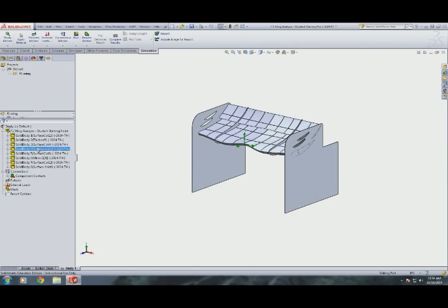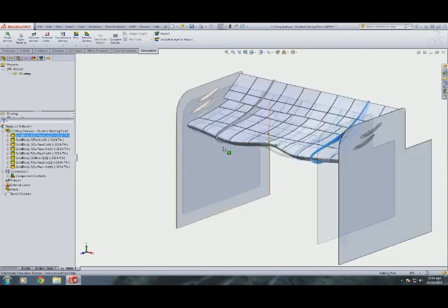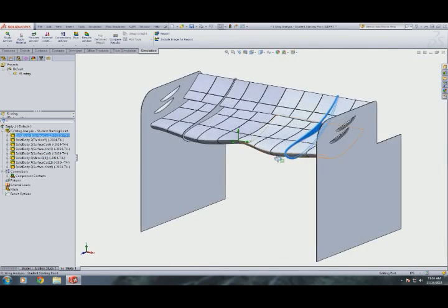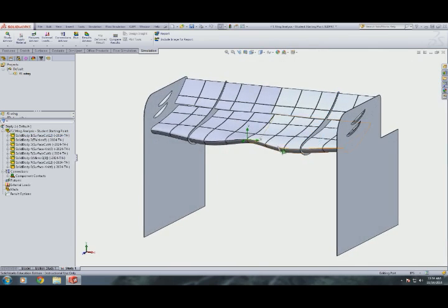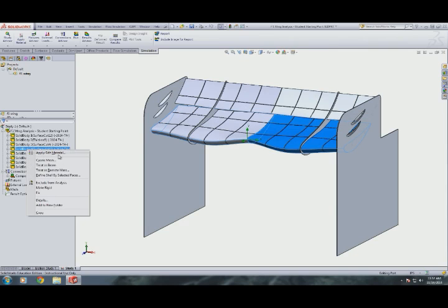So the next thing we need to do is actually start considering how to hook up the internal structure to the surface of the wing. Right now, remember this wing is a solid body. I made the modification in the part you downloaded. So obviously you're not going to cut this wing out of a solid chunk of aluminum and put it on your F1 car. The way you figure that out is we can find the solid body that is the big wing, right click on it and say define shell by selected faces.